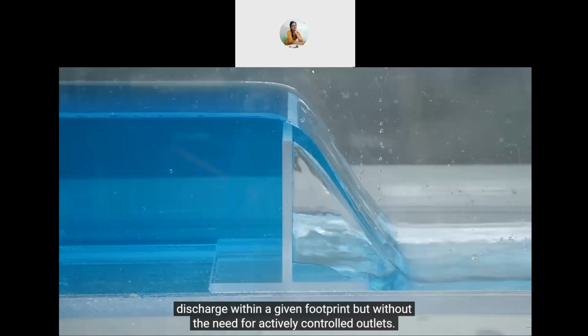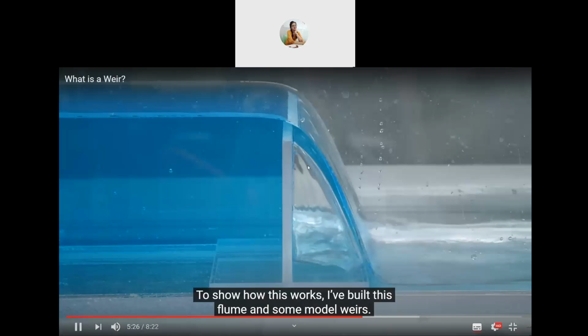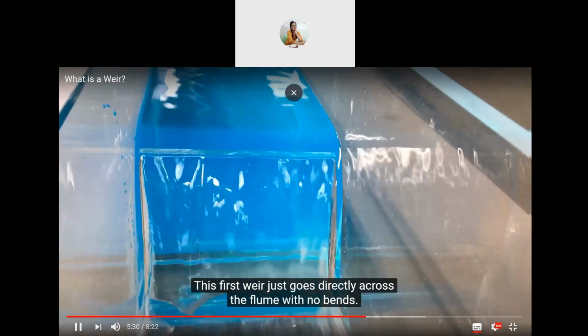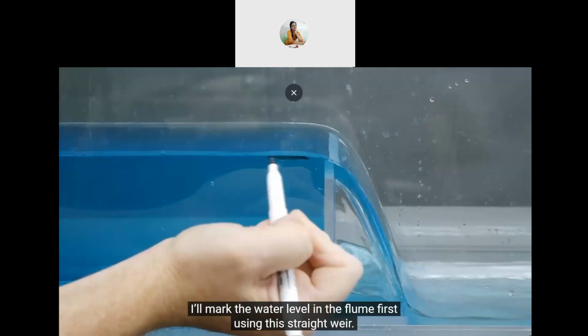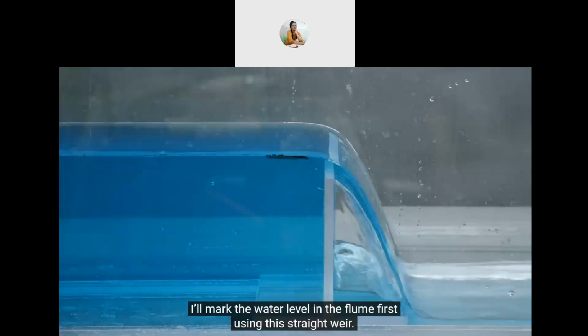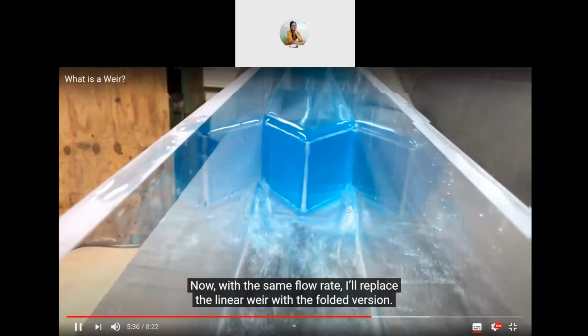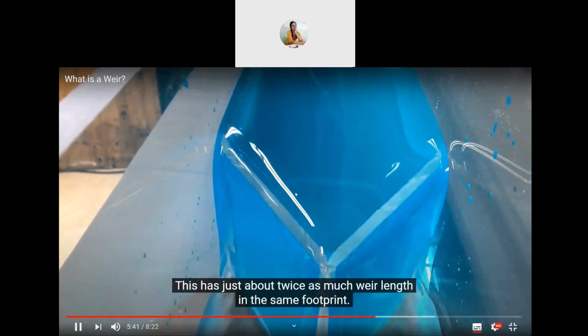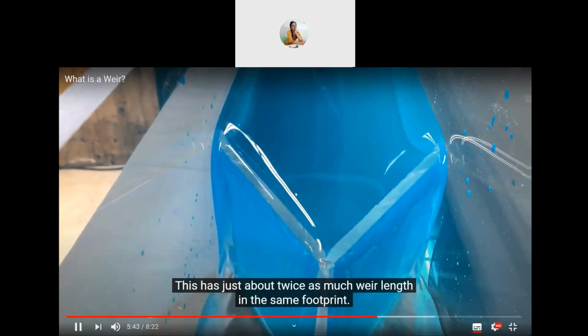To show how this works, I built this flume and some model weirs. This first weir just goes directly across the flume with no bends. I'll mark the water level in the flume, first using the straight weir. Now, with the same flow rate, I'll replace the linear weir with the folded version. This has just about twice as much weir length in the same footprint.